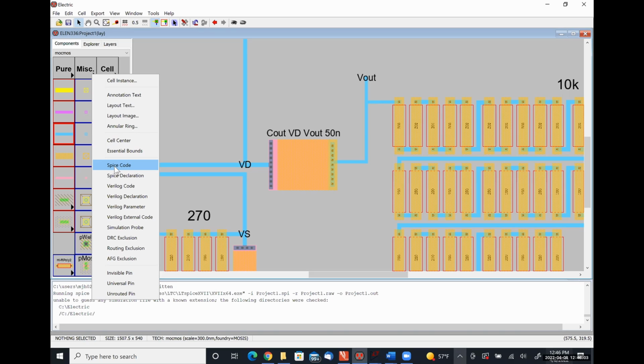The reason why we're doing it like this actually is because in the assignment sheet, you were told that the capacitance per unit area between poly 1 and poly 2 was 200 picofarads per micron squared. For a real C5 process, it's about 850 femtofarads per micron squared, which means your capacitors would be on the size of like a millimeter by a millimeter.